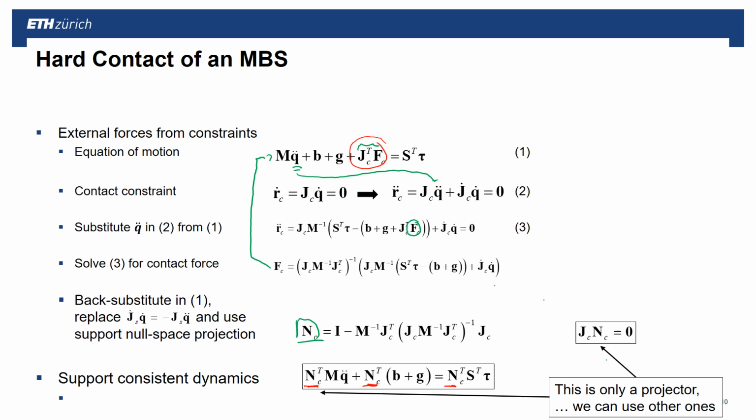So in this slide we see everything we need. We see on one side the contact force, which is a function of the constraint. So given my constraint, given my actuation, and given the current state, we can directly calculate the Fc. This is the first element which is important. The second element is that we can rewrite the equations of motion independent of the ground reaction force.